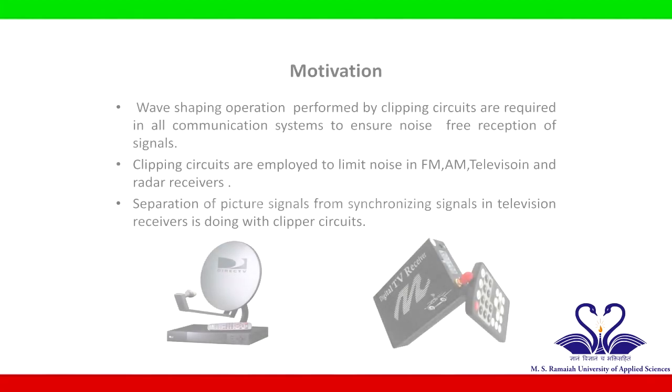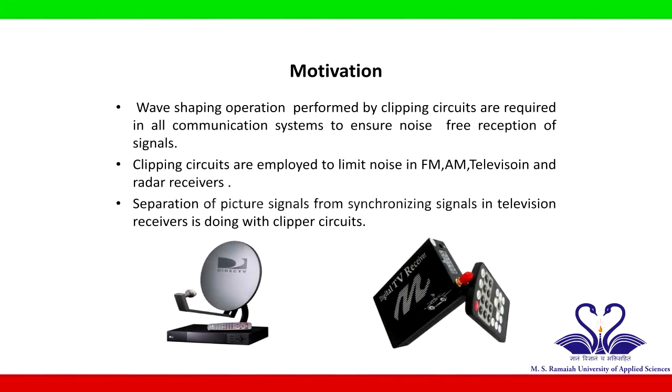Motivation for this experiment: wave shaping operation performed by clipping circuits is required in all communication systems to ensure noise-free reception of signals. Clipping circuits are employed to limit noise in FM, AM, television and radar receivers. Separation of picture signals from synchronizing signals in television receivers is done with clipping circuits.